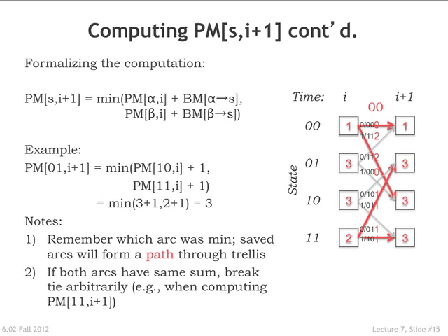Yeah, so what you're saying is that if there isn't a unique way back, then you're not certain. Well, you're never certain here in this business. You're just doing your best guess. So when you commit to one particular choice when there are two equally likely costs, you're saying the probability of error is going to be the same with this choice as it will be with the other choice. And in the end, that's what we have for the metric. It is unsatisfying, perhaps. Now, there are schemes where you'd keep a list of the possibilities and try and do something with that, because maybe there's some higher level thing that would help you disambiguate between possibilities, but that would complicate the processing. But as far as this goes, you make a choice and you move on. All right.